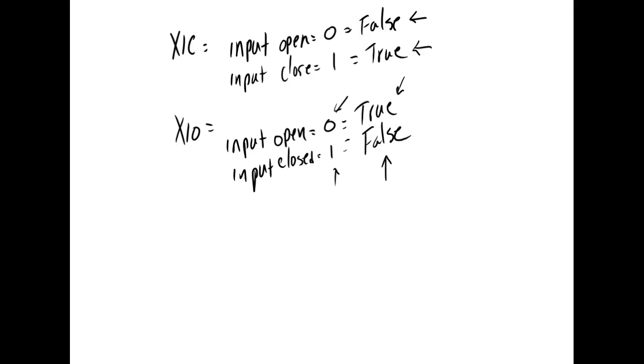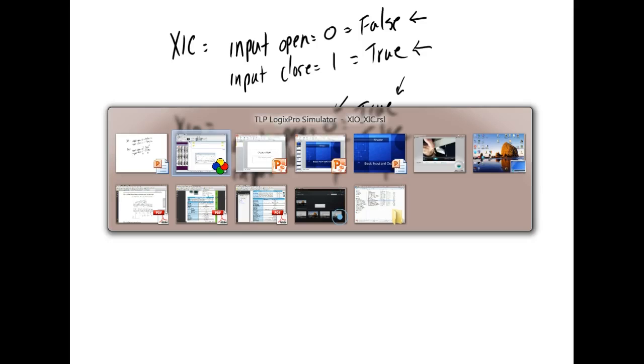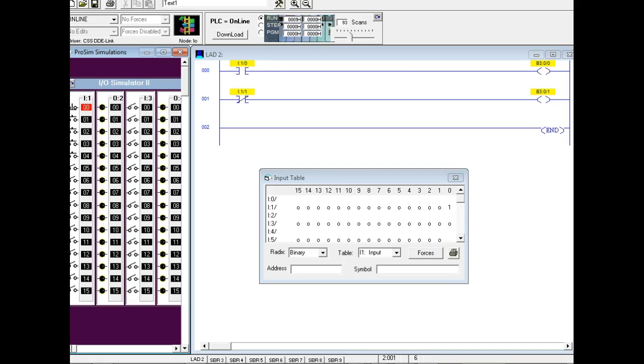So guys, I don't know how else to show y'all that. Especially on an e-stop circuit, you don't have to use a normally closed contact, but I want it to be true, right? If it's pressed, it's true. I'm sorry, if I get a 1 back, it's true. The problem is, if I get a 1 back, I have to use a normally open contact symbol.